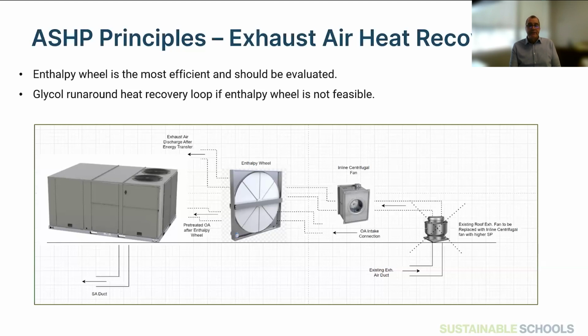The VRF areas of those same schools, we do have electric baseboard heat in the admin areas and in the perimeter offices for the principal and the vice principal. Our common areas, like our learning commons and some of the corridor areas, we don't have backup heat, and we're finding that with the VRFs that we're using, we are able to keep the spaces right around 21 Celsius.